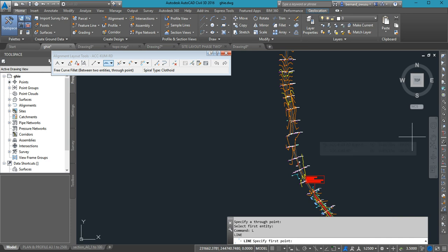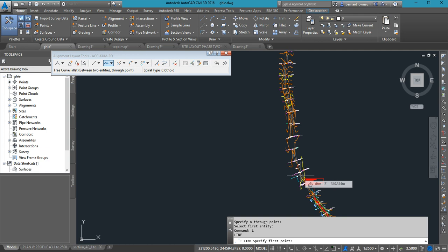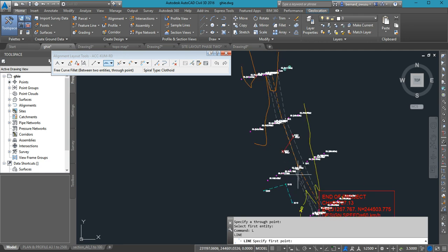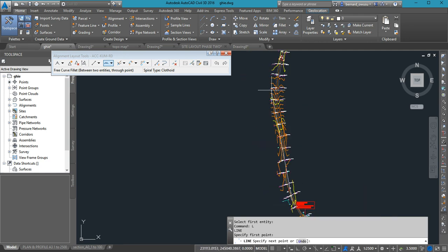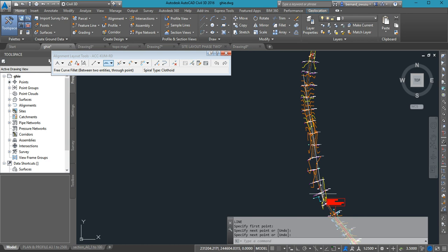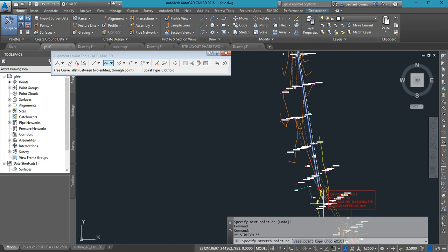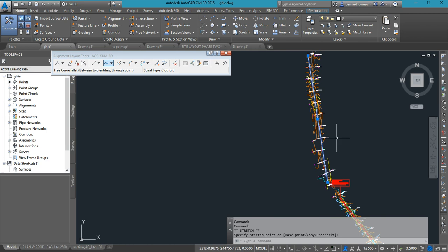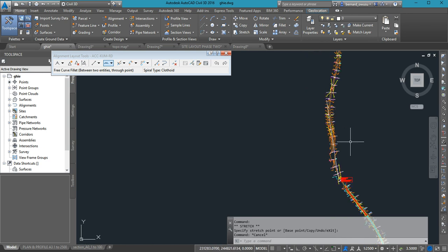It should also be in order of increasing chainage. So I'm going to draw my center line for the third tangent. It appears there is a little curve, but we are going to straighten it up. So I specify maybe somewhere here. Then I open it up to maybe somewhere here. Have you seen what I've done? So try and do something like that. So this is my third tangent. But this time I've used the ordinary AutoCAD line to draw it. Very, very simple.